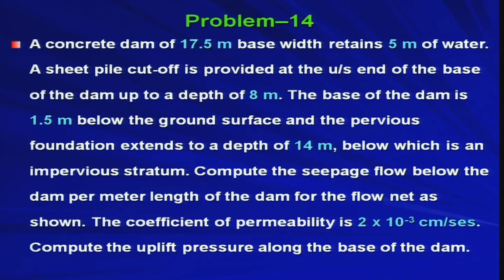Today's first problem is a concrete dam of 17.5 meter base width that retains 5 meter of water. A sheet pile cutoff is provided at the upstream end of the base of the dam up to a depth of 8 meter. The base of the dam is 1.5 meter below the ground surface and the pervious foundation extends to a depth of 14 meter, below which is an impervious stratum.